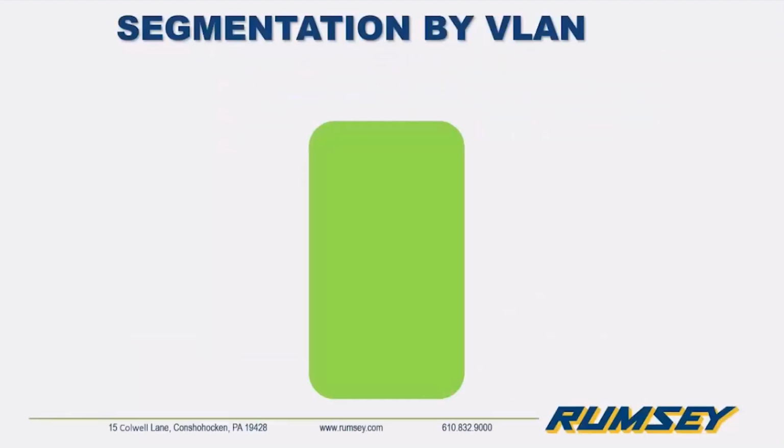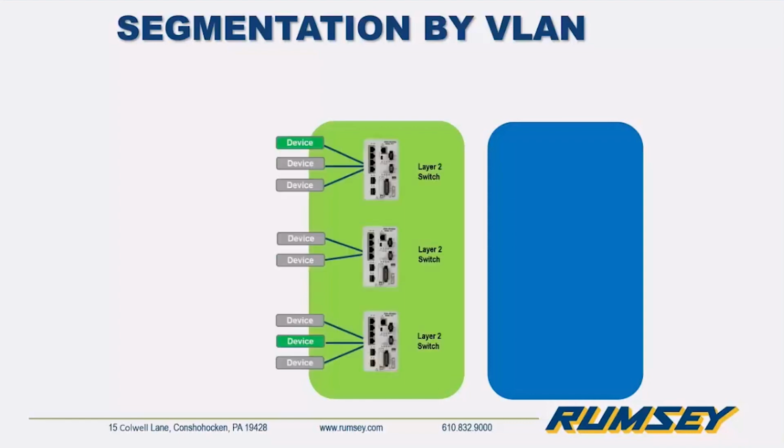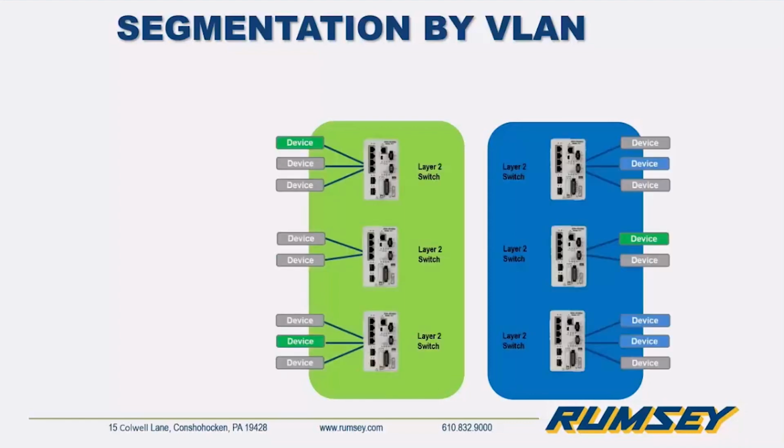Take this example. We have a process facility. This green area is a process area. Blue is a packaging area. Each area has 3 machines that are linked together. So recently, cameras, for example, have been placed on these automation control switches, but it's resulted in rampant problems because they consume so much bandwidth and disrupt the control network. These cameras are used in both the packaging and process areas, and they operate together.